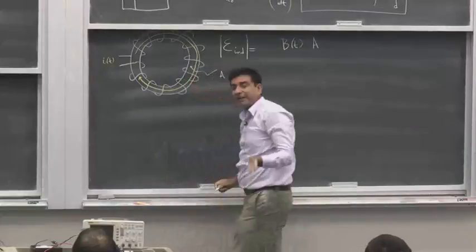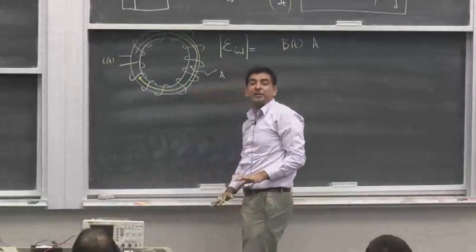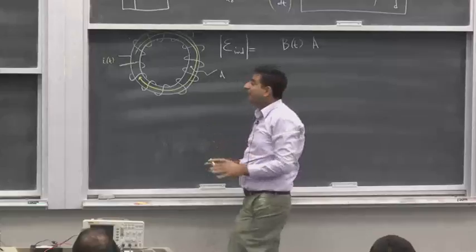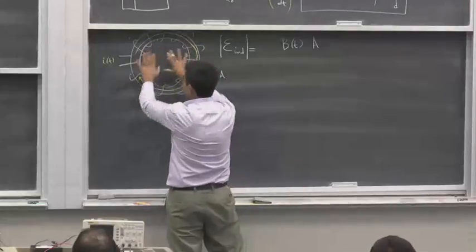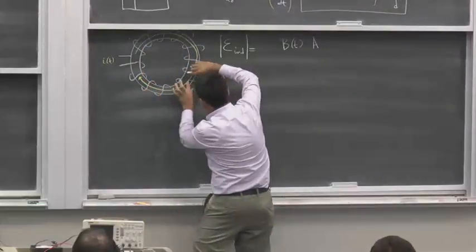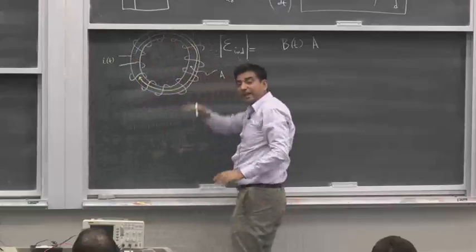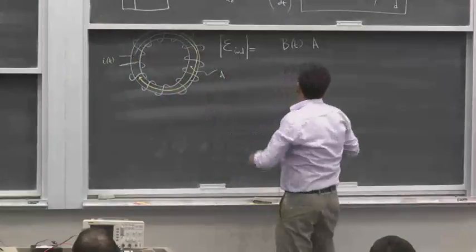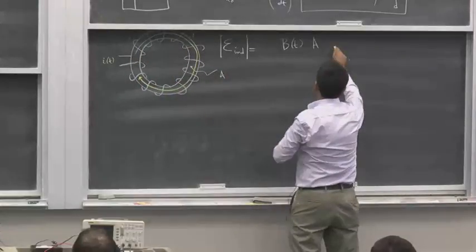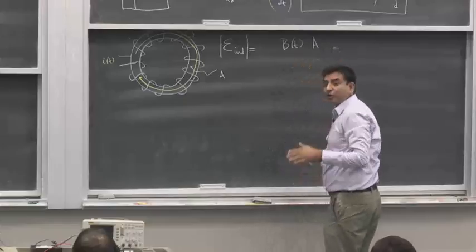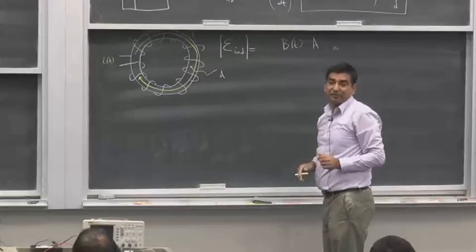Remember, you have to choose your areas properly. I'm noticing that you don't choose your areas properly. Here the area is not the area inside this frame, it's the cross-sectional area of this donut, because that's where the magnetic field is. So this is the induced EMF, but the magnetic field, we've already calculated the magnetic field inside the toroid.